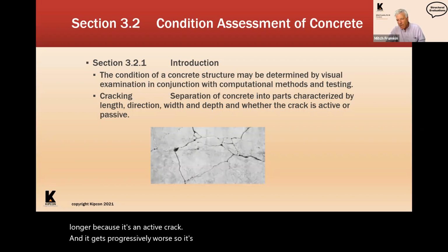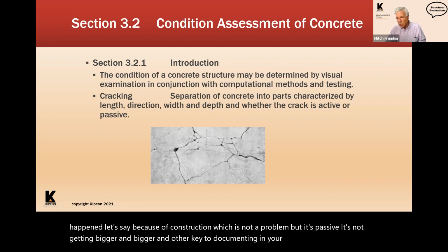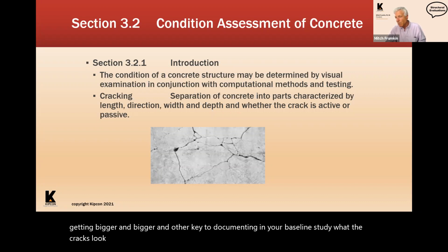Versus a passive crack, a crack that may have happened, let's say, because of construction, which is not a problem, but it's passive, it's not getting bigger and bigger. Another key is documenting in your baseline study what the cracks look like, so you can go back a year later to see if they've gotten worse.